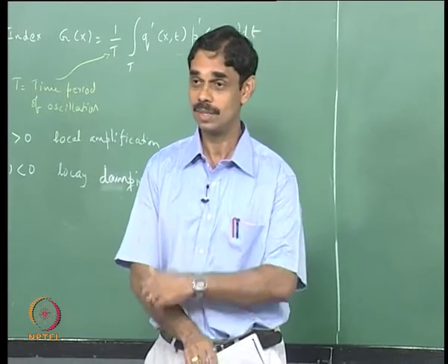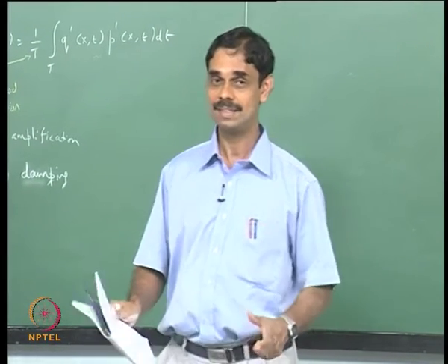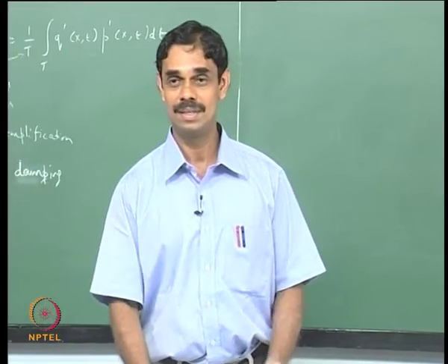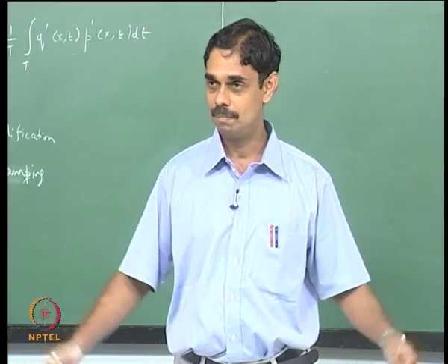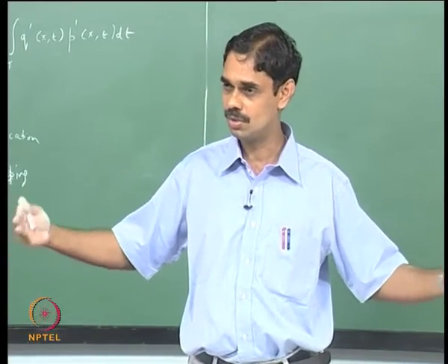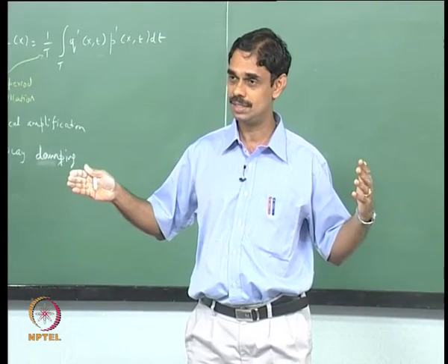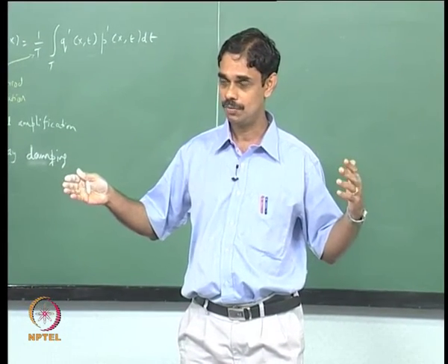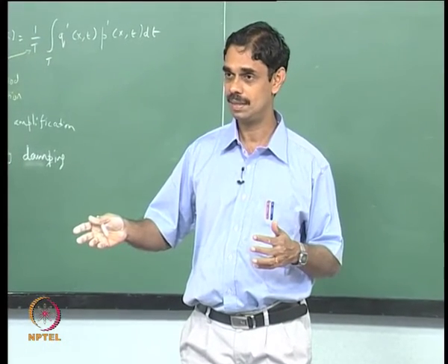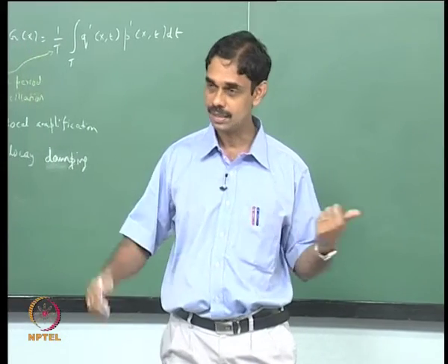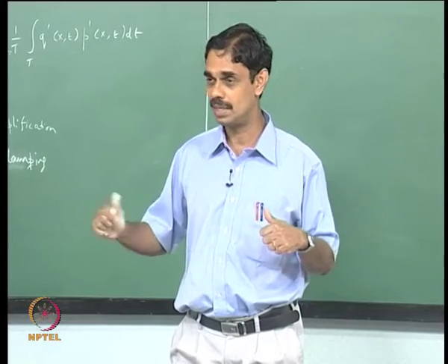It's a very good question. We'll answer this by recalling what we did for admittance and so on. When you have a perfect example like closed and open end, we always got the phase difference between pressure and velocity as 90 degrees, pi by 2. But if you have a left traveling wave and right traveling wave, you always got it as 0 degrees or 180 degrees. For the right traveling wave the velocity was P prime over rho c, and for the left traveling wave it was minus P prime by rho c.